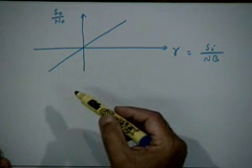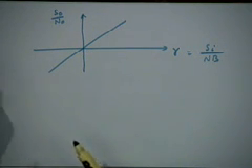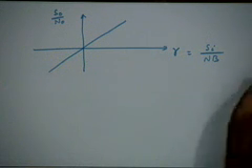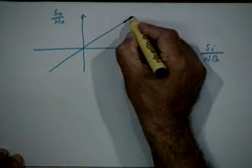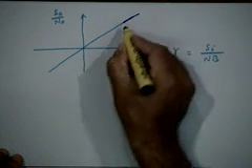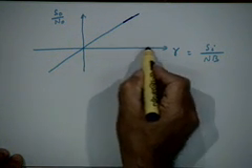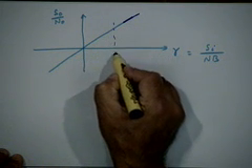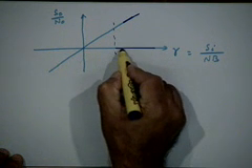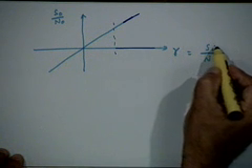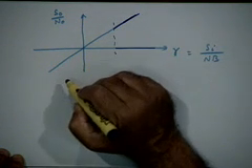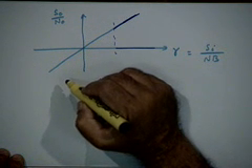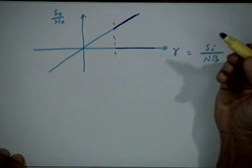But what do we find now? Our finding now is that in the case of the envelope detector, as long as the SNR is high, that is you are in this kind of region, let's say above some value, if your input signal is much stronger than the noise, you are more or less on the same curve, right? Because the two expressions are the same.